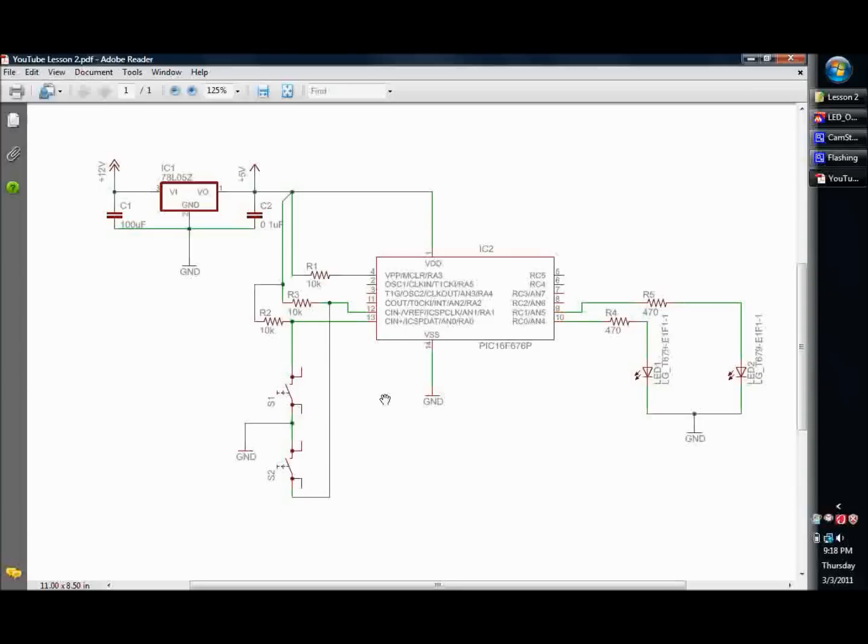Some chips have their own onboard flash memory that you can store things in for later use, but sometimes that tends to be limited, or you may have to increase the size of the chip or go to a higher type chip like an 18F series, which could be higher than the 8-bit series that we're using, the 16F. So you may add some external flash memory, as well as maybe some other things like a Dallas Semiconductor 1307 chip, which is a real-time clock that utilizes the I2C bus, and just things like that. That's kind of some prelude to the future.